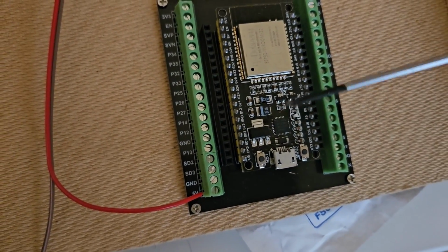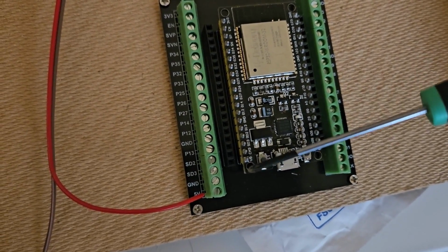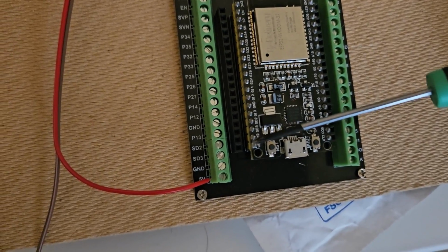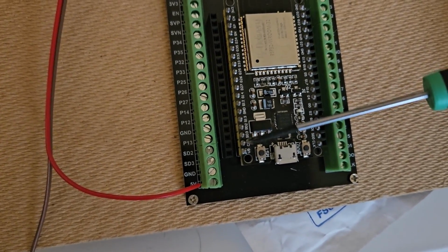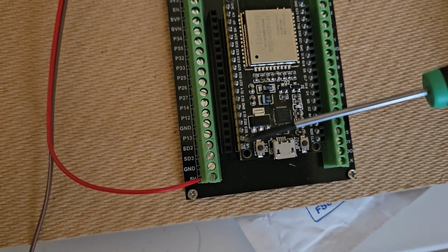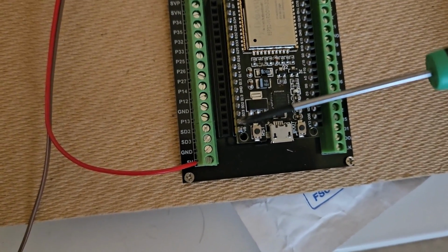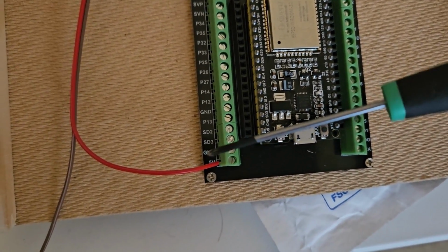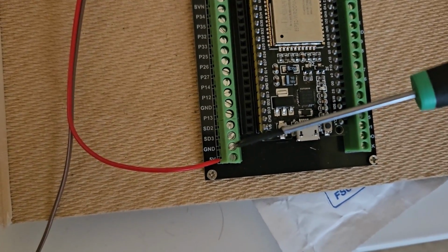And I went and had a look. I've got pictures that I use for reference because my eyesight isn't really good enough to see this stuff. But actually, the next pin up from 5 volts on here, according to the images I've got, is I think GPIO 11, which is labelled CMD. Now I don't know what CMD is, command, whatever it is, but that's not ground, that's not GND. So they made a mistake down here, and I don't want to be connecting a ground cable to GPIO 11.